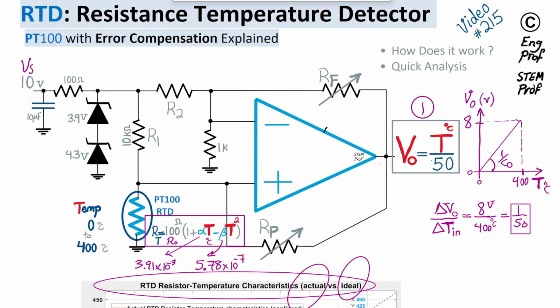Because the circuit is stable, we also apply a 10-volt supply and ground for the two supplies of the op-amp. The op-amp is forced by dominant negative feedback into the stable region, and therefore the virtual short is valid for the op-amp, which states that the positive and negative input terminals of the op-amp should have the same voltage, which is the voltage across the RTD resistor, VR. That would be VR here, and therefore VR here, which means we have VR here.